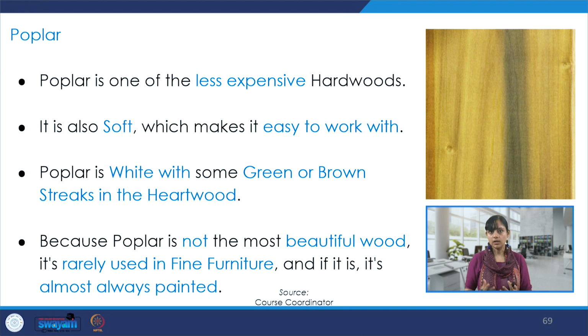Then there is poplar, which is not a very popular wood even though it is less expensive, and for a hardwood it is soft and easy to work with. But because it has some kind of streaks of green or brown that you see over here, sometimes it is less popular amongst designers and clients. So it is not considered one of the most beautiful woods, therefore it is rarely used in fine furniture. And if it is used, it's usually painted.